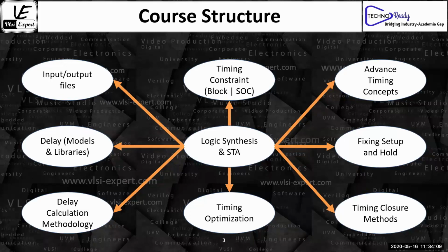We will give you a little bit of an idea about the PVT corners, RC corners, and when we are talking about MCMM, what is the meaning of multi-mode, multi-corner. Those things we will cover in the advanced timing concepts, because these are the things which are going to confuse a lot of people, and they are not able to understand how changing the switches between these things is going to impact my STA or the synthesis or the PD flow.